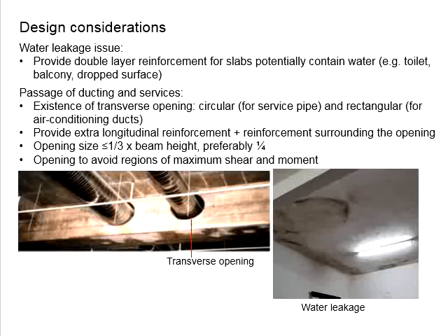But ultimately, if you have a problem with water leakage, it will lead to structural problems in the long term. You are afraid of the corrosion of the steel embedded in the slab. When this is excessive, it will lead to structural problems. There will also be watermarks on the ceilings or on the floor slab, which is going to raise concern from the occupants of the buildings.